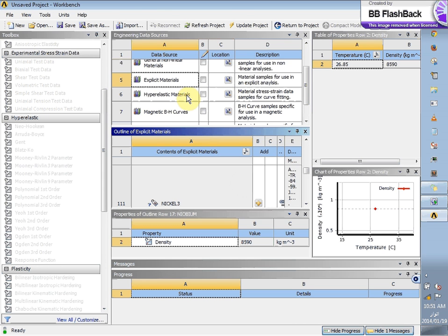But when the foam is compressed in its elastic range, where if you remove the load it will come back to its normal state, its density will change. You will see it getting thicker, then softer and less dense, and then high density foam just by applying load. These types of materials are called hyperelastic materials. So you can model these foams there too.